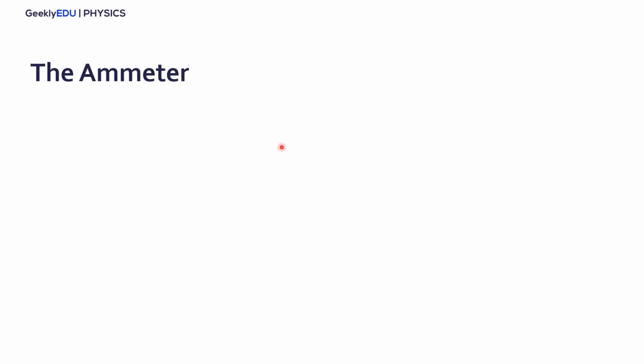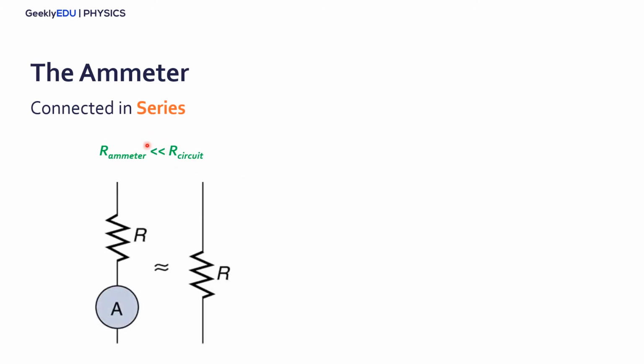Now for the ammeter, it's basically almost the opposite of the voltmeter. For the ammeter, we always connect it in series in the circuit, and we want the resistance of the ammeter to be much lower than the resistance of the circuit. Again, this is so as not to alter the circuit, because now it is in series. If the resistance of the ammeter is much lower than the resistance of the circuit, we're not altering the final resistance.